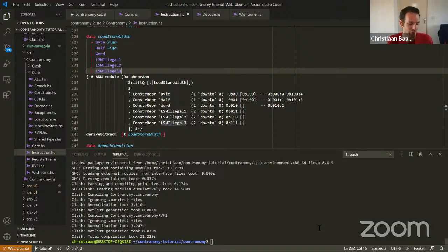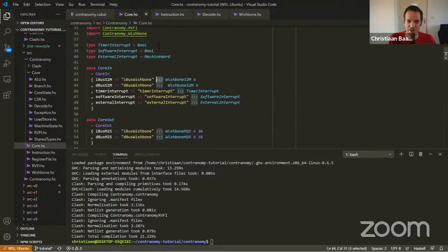So yeah, that's it about some of the non-Haskell parts of Clash that you might have to think about, bit encodings, or making sure that the generated ports are named correctly. Otherwise, Clash will just do the right thing. It will pick encodings which are suitable.